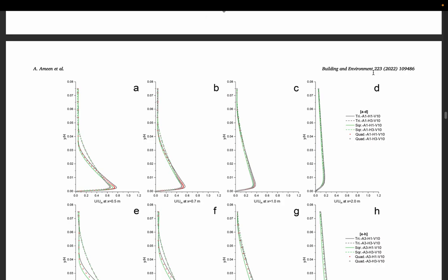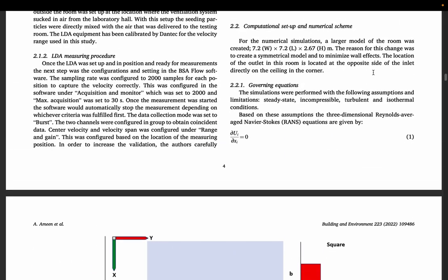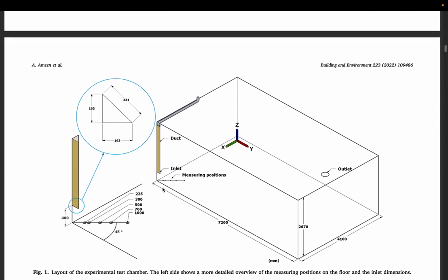That depends on case to case. In this particular scenario, their objective is to understand how this flow is distributed from the inlet. So from here, how is my flow getting distributed as it goes away from the inlet? They want to understand that. So depending on that, they will see, by refining the mesh, whether those particular velocity values are changing or not.